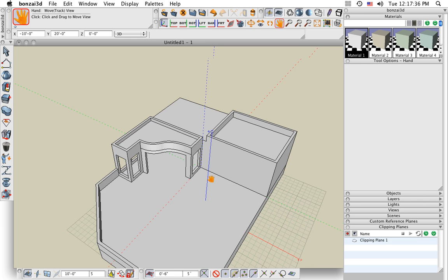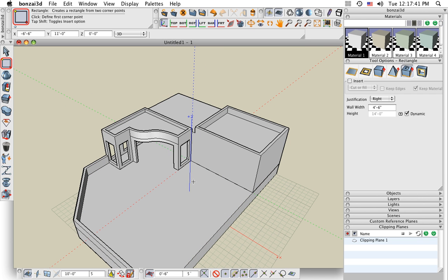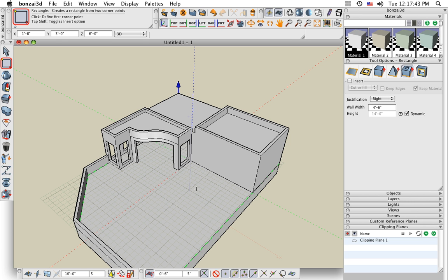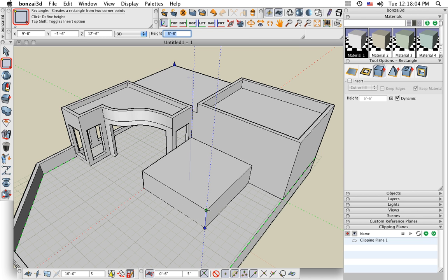All right, let's add a few more pieces here. How about a platform there in the middle? Again, I'll adjust my reference plane. Back to the straight extrusion drawing. Snap to the corner. Draw a rectangle. And by the way, this purple line is a diagonal. So if I snap to it, I get an exact square. So no need to be precise with the numbers. Just snapping does this automatically for you. Extrude it up maybe 6 feet.